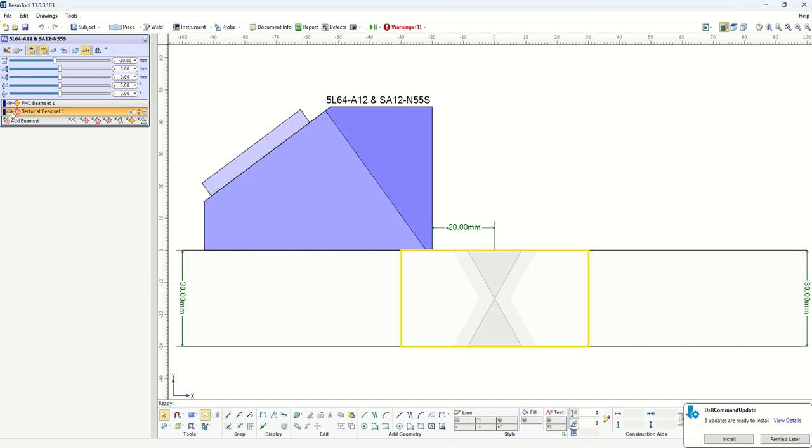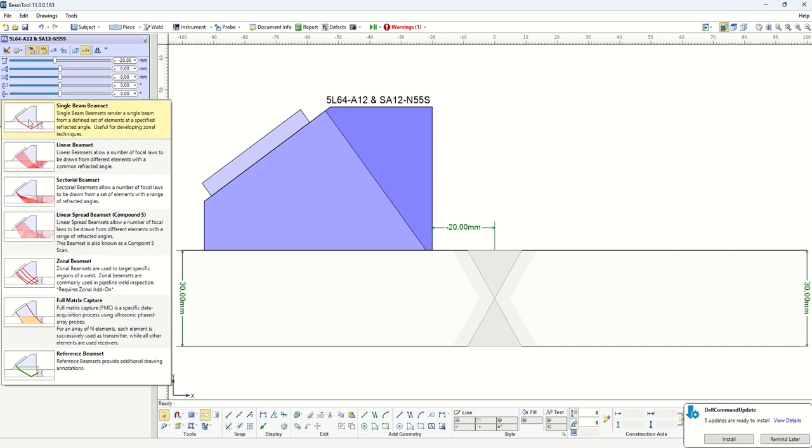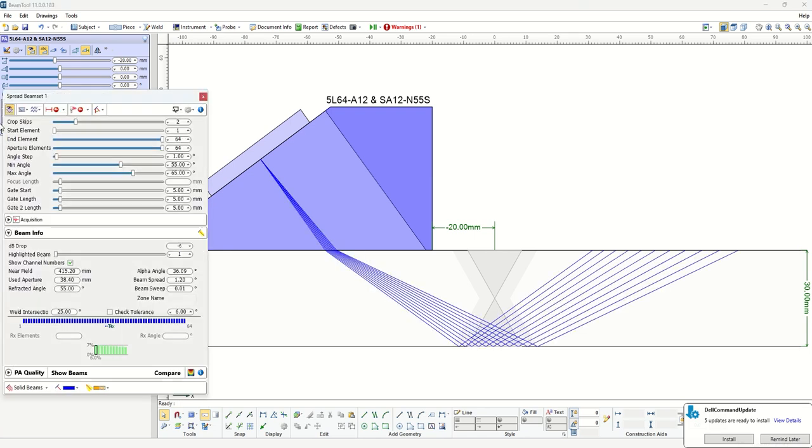Now let's look at another example of a technique designed for covering this weld. Before that, I want to just show you how we can use point spread function to assess focusing capability in phase array inspection techniques. In this case, what I want to show you first is the design of a compound scan, as we did before. If you remember, we introduced the compound scan, which is the beam set that we can create different beams from different apertures.